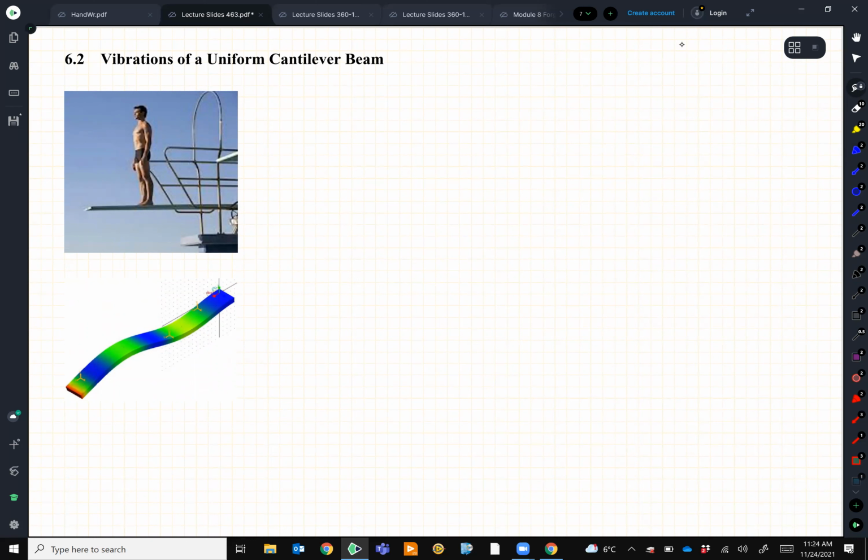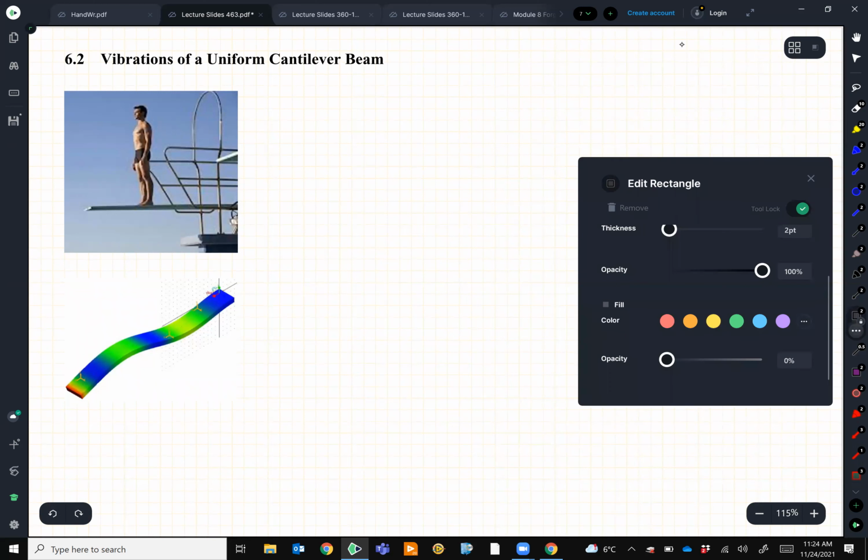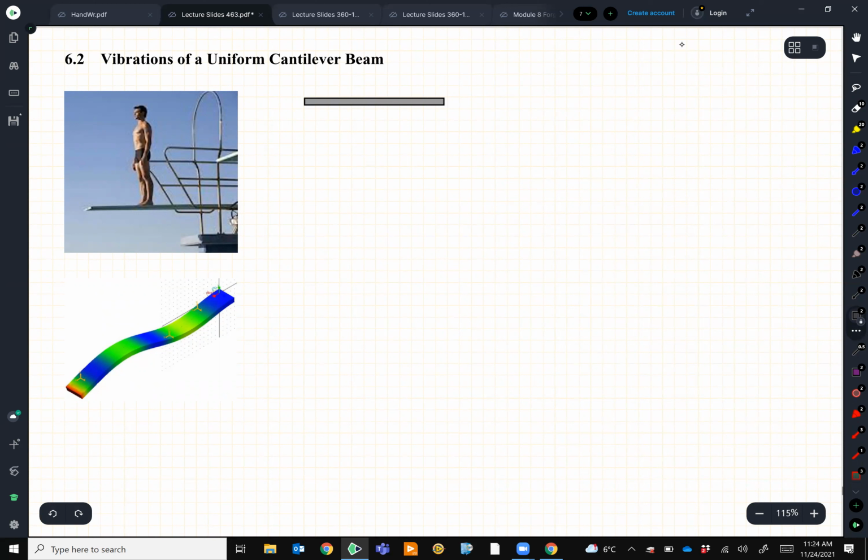All right. So like always, we need to start with free body diagrams and deriving the equations. We use Euler or Lagrange, or Newton, that's the tool that we have. And let's see what we get. Let's start with a simple beam. Let's say, in general, I have a beam, and for now, I don't identify the boundary conditions.